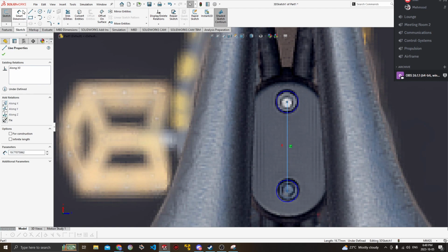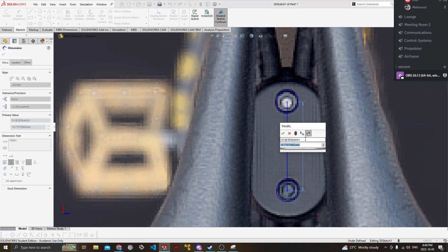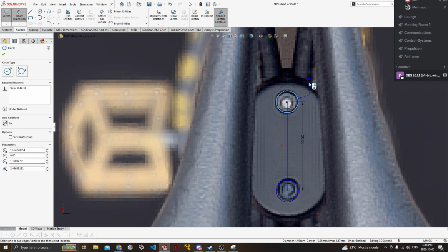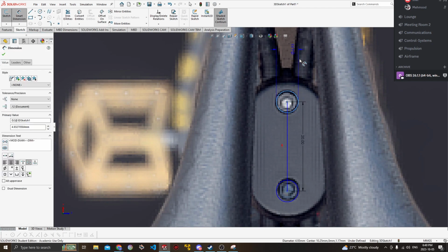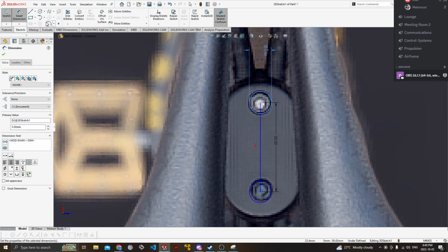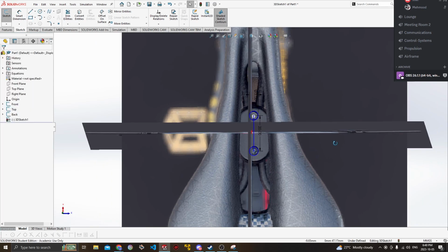Okay, I want to take the smart dimension now. This is 19.77, so we're just going to set it at 20 millimeters. Find these as 5, so they're most likely M5 screws that are 20 millimeters spaced apart. We're going to grab a, what is the tool? Dimension. Okay, that should be good for now.